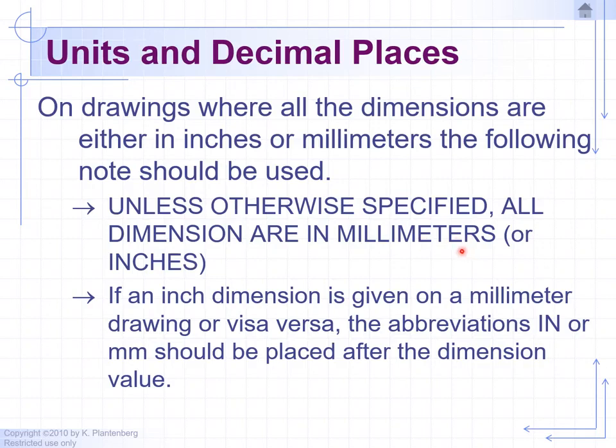So you're not going to label each dimension like the dimensions that you saw in the previous slide. You're not going to label every dimension with 1.25 inches, 0.59 inches. You do not include the units because it's already in the title block.